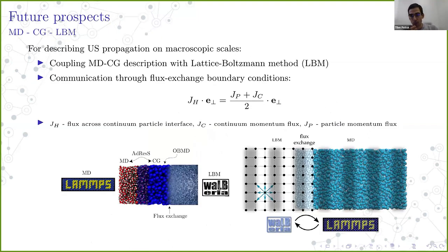And as a future prospect, if you're really trying to describe the ultrasound on macroscopic scales, then you need to couple it to a solver for continuum hydrodynamics. One ideal candidate for that is the lattice-Boltzmann method. There we would use the waLBerla solver.